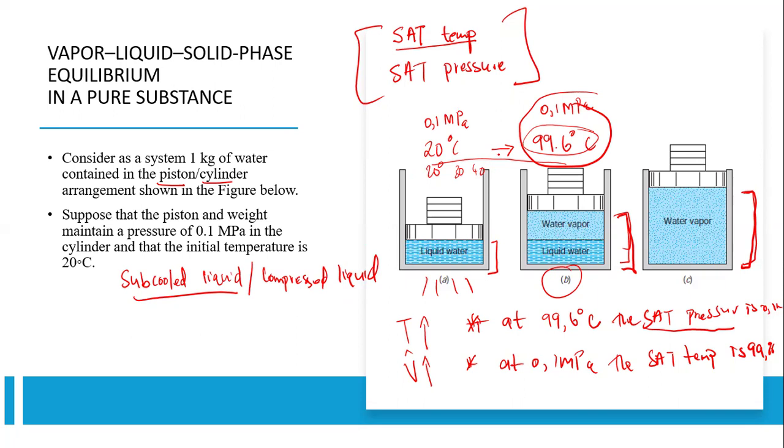temperature, it is in possession of that temperature, we say that the liquid, which is a pure substance, right? We say the pure substance exists as liquid. In that case, it is called the saturated liquid. Sorry, I'm confusing subcooled and compressed and saturated. I'll explain this later on. So, subcooled liquid is the liquid that exists below this temperature, below 99.6 degrees Celsius, meaning this liquid over here is called subcooled liquid.